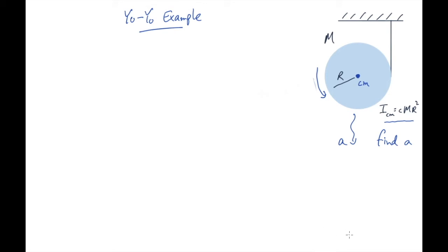What we will need, though, is the no-slip condition on the velocity, which tells us that the tangential velocity is r times omega, and we'll need the work-energy equation. The work done by other forces that we have no potential for equals the sum of the mechanical energies, kinetic plus potential, equaling the sum of the kinetic and potential energies at the end of the motion.